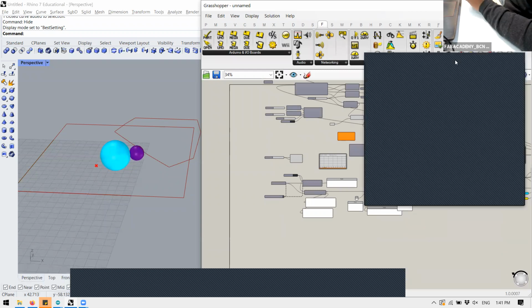The visualization is always like right now, it's only inline, but is there a way to exploit that as an outlet or something? No, no. The closest way to get out of Rhino, let's say the visualization interface, is using another plugin of Grasshopper called Human UI that allows you to create interfaces, but you need Rhino running in the back. So you can have it minimized and have your own interface, like a proper interface, but you have to have Rhino running. It's the same as you can listen to music in Spotify without having Spotify showing. Human UI is quite easy to work with. It's a nice, clean way to make interfaces.